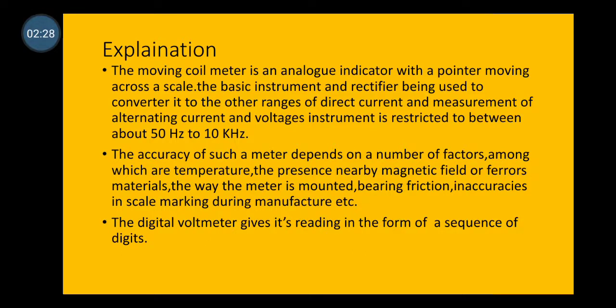The accuracy of such a meter depends on a number of factors, among which are temperature, the presence of nearby magnetic field or ferrous materials, the way the meter is mounted, bearing friction, inaccuracies in scale marking during manufacture, etc.